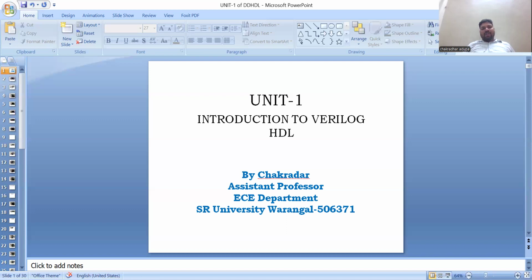For example, 12'b1111_0000_1010. Here it is a 12-bit binary number, starting with 4 ones, then 4 zeros, and finally 1010. For readability, putting an underscore between groups of 4 digits helps the reader to analyze and read the 4 bits. 4'b10?? is equivalent to 4'b10ZZ.